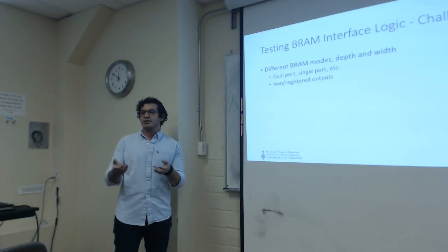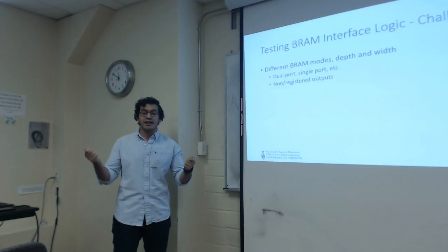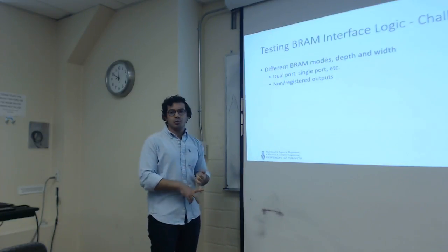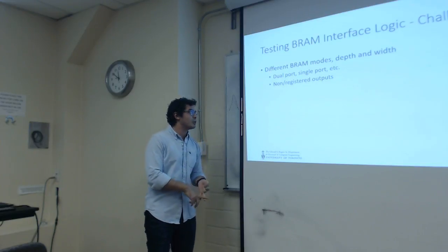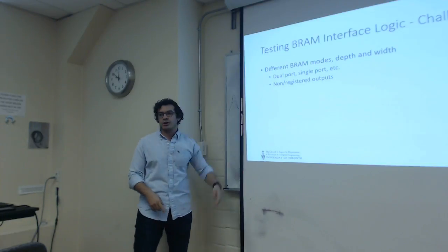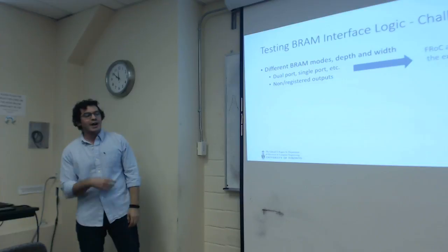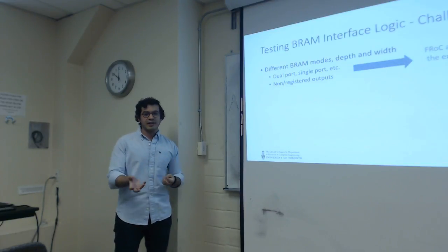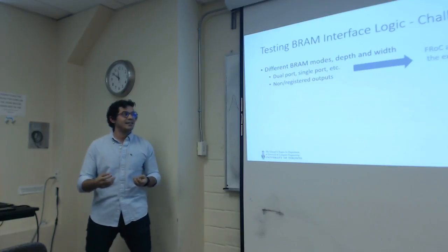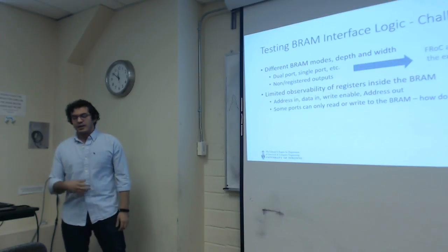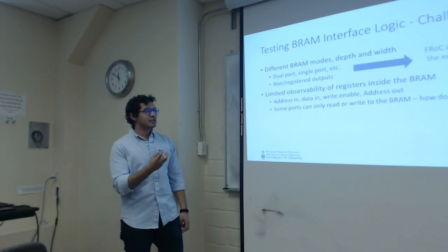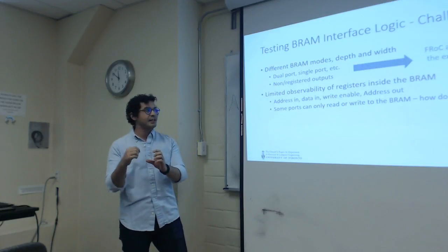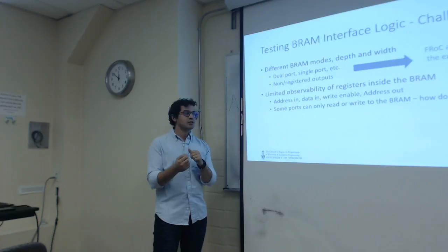So comparing these paths to just a regular path that starts and ends in the soft fabric, the BRAM itself could have different modes, different depths, different widths. It could have registered or non-registered outputs. So to handle these issues, our tool analyzes the BRAM used by the user, and we replicate the exact same mode. The other major challenge is that these registers that are inside the BRAM are buried inside. You have no observability on the input or the output of these registers.